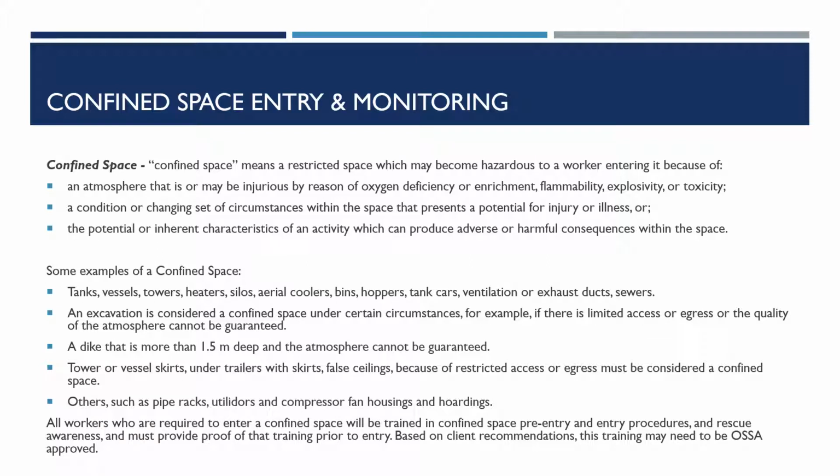Confined space entry and monitoring. Confined space means a restricted space which may become hazardous to a worker entering it because of an atmosphere that is or may be injurious by reason of oxygen deficiency or enrichment, flammability, explosivity, or toxicity, a condition or changing set of circumstances within the space that presents a potential for injury or illness, or the potential or inherent characteristics of an activity which can produce adverse or harmful effects within the space.